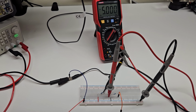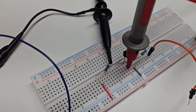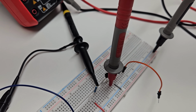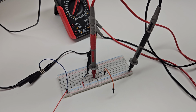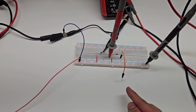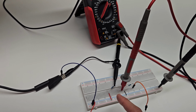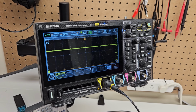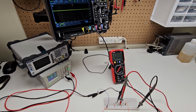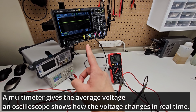To demonstrate the importance of pull up and pull down resistors for transistors, I built this test setup and now I'm measuring the collector of an NPN transistor with no pull down resistor. So we are reading 5 volts. It's open, so the transistor is off. We are reading 5 volts on the collector side, which makes sense. This is how it looks on the oscilloscope. The moment I touch the wire, look what happens.